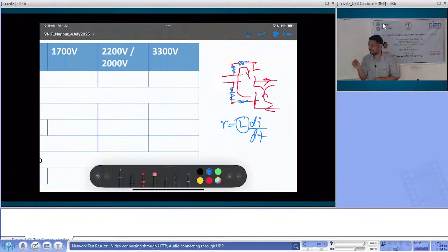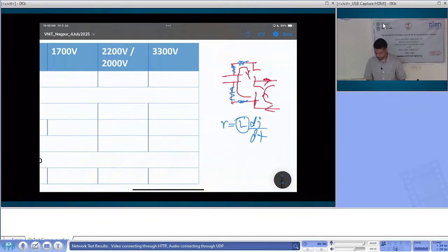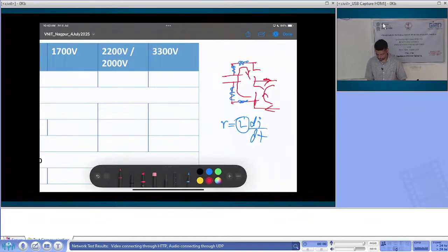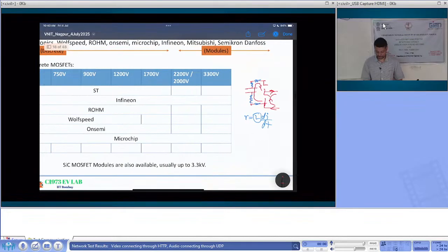You will see that the GaN devices come in very tiny packages, right? The reason is that you can connect them in a really closed loop fashion, so you minimize the inductance value. So basically, yes, discrete gives you more flexibility in trying your own design, both in terms of topology and in terms of the placement or the optimization part. We have also used discrete for some other applications, and for this application for now we are going ahead with discrete, but we have used modules for some other applications as well.